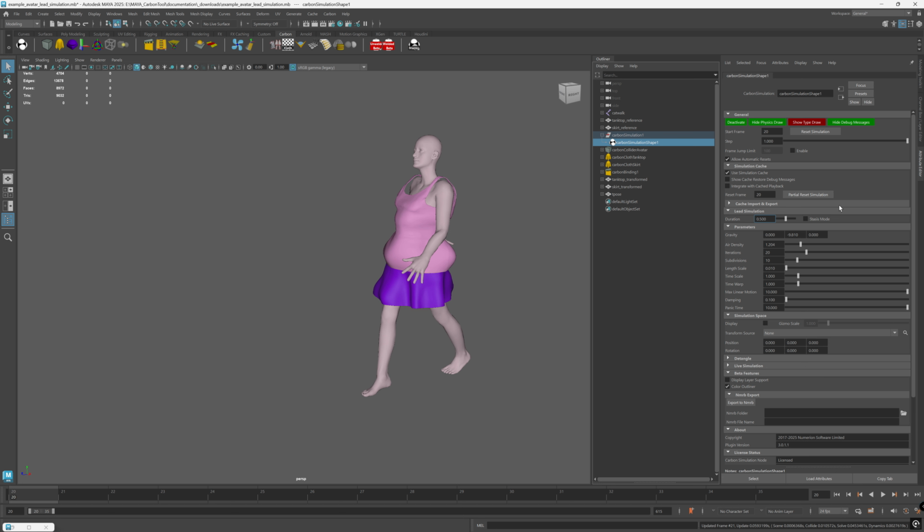Stasis mode. Stasis mode triggers a dynamics integration that ignores all action forces and wipes out all kinetic energy, reducing motion and deformation to only results from the reaction forces generated by constraints such as collision, joints, or soft primitives. In practice, every dynamic object feels like it's in clay that can be sculpted. So for example, this turns off gravity, or if one thing knocks another one, it's not going to keep moving. It just basically stops as soon as the collision is done. So you can either tick it on or off.